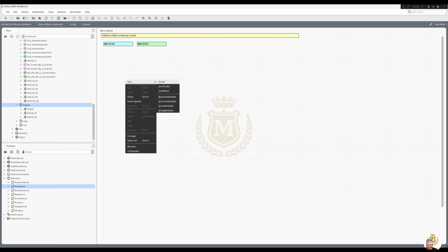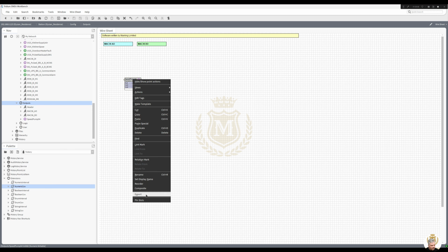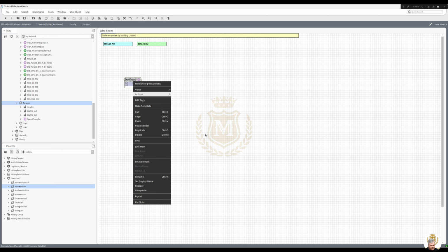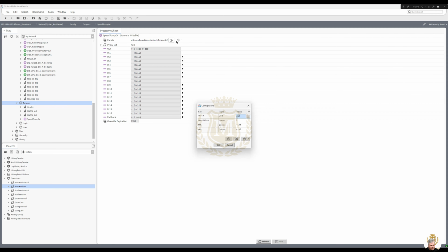Analog output, so it's got to be a numeric. And AO1 is pump 04 speed control. Speed pump 04. Pin slots take out in 16. Action set to 0. We're going to be using 0 to 100%.